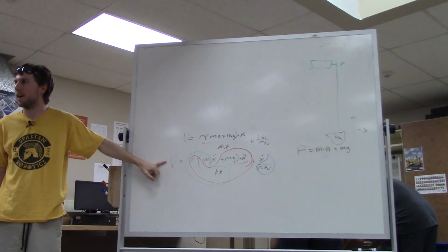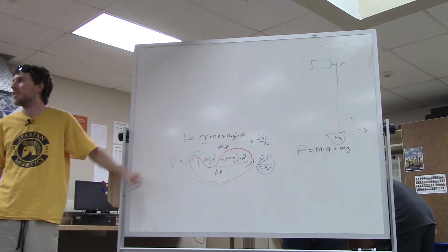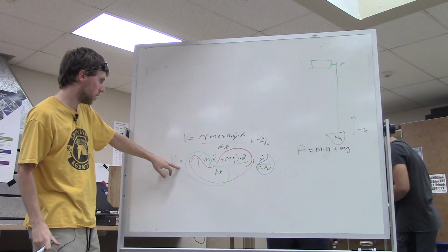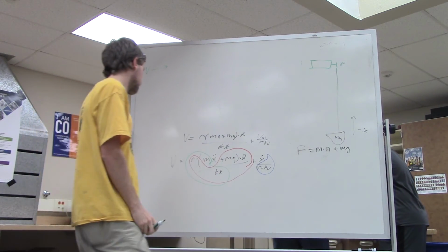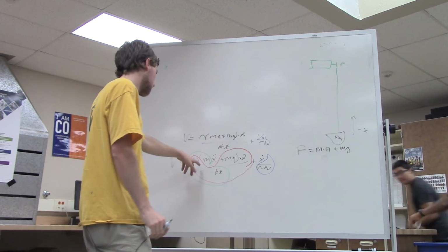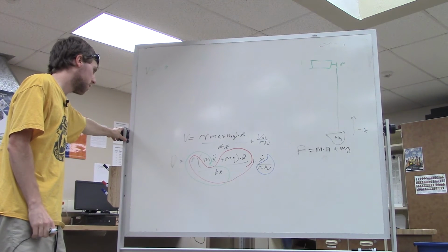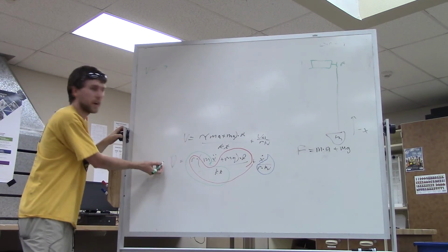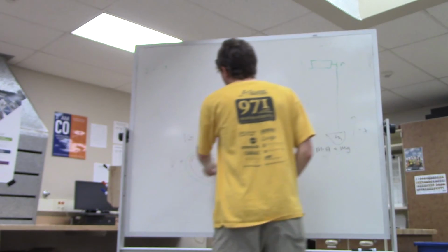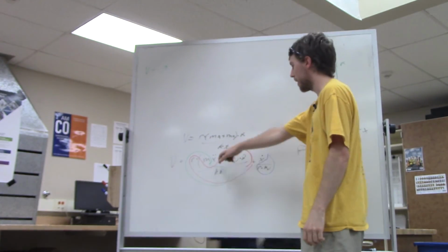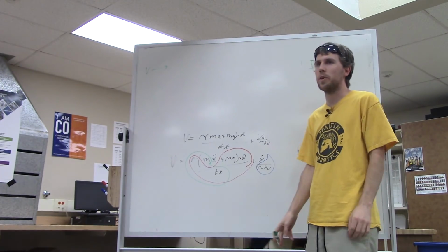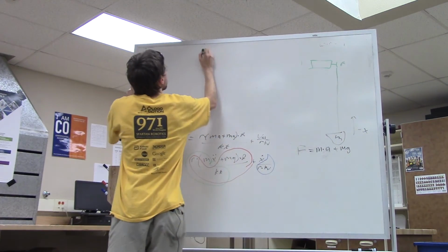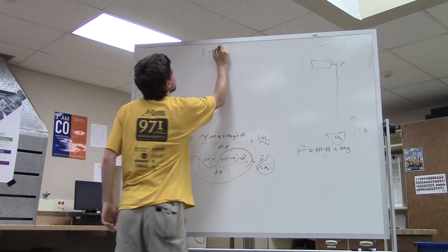So we need to develop the block diagram for this, right? We have a voltage coming in. We need to refactor this equation a little bit first. We want to get something in terms of x double dot, so then we can integrate it. And this is actually what you would want to do for simulating it anyways. So we need to get x double dot on one side and everything else on the other. So we have V minus x dot rkv.